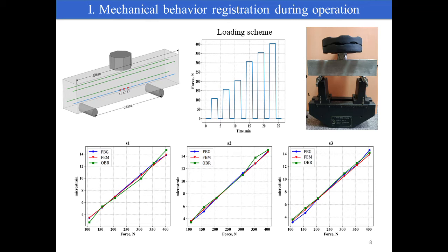In the course of the experiment, a stepwise increase in the load was carried out, holding the constant load level at each stage for 2 minutes and unloading before each stage of loading. The obtained experimental results from FOSs were compared with the result of numerical simulation by the finite element method. The high sensitivity of the FOSs should be noted, which makes it possible to measure even small levels of strain. The experimental results showed a close to linear behavior of the material at these load levels and a good agreement with the result of numerical simulation.